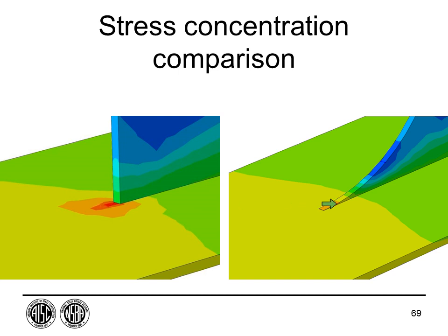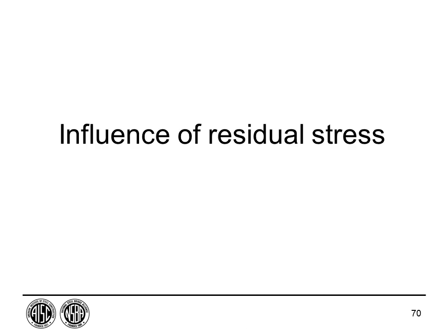But if I smooth that out and put a nice round radius, well, I get rid of those high stresses, and I don't expect fatigue cracking to occur as likely for a given stress range at this location. And in fact, I could maybe even have infinite life with the higher fatigue resistant detail. So geometry plays a major role in fatigue cracking or likelihood of fatigue cracking, which is then reflected in various details. The other factor we talked about was residual stresses.